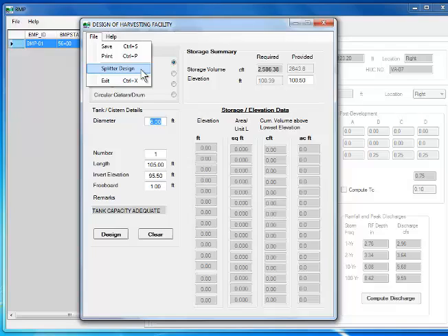These are provided as part of the treatment train, to help achieve the desired treatment credit, when demand is not enough to sufficiently draw water levels in the tank down between storm events. Low-flow diversions or flow splitters in the form of a weir, or curb opening sized for the treatment volume help minimize clogging and reduce the maintenance frequency.